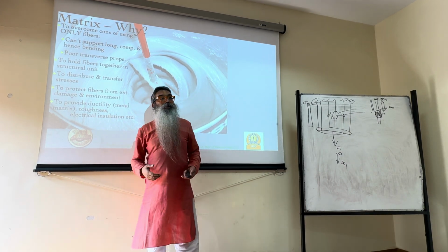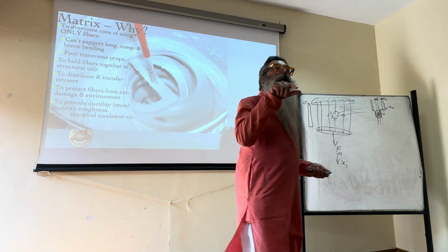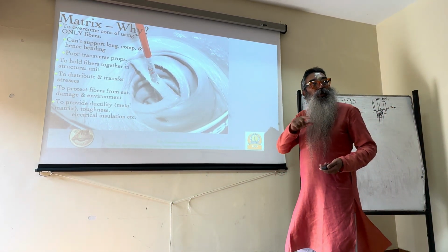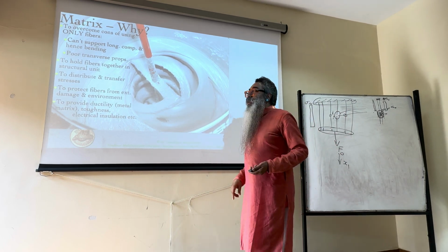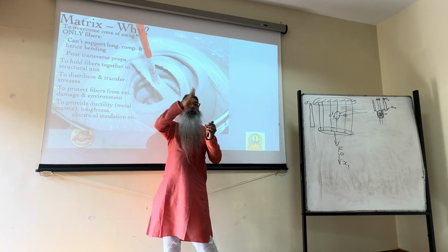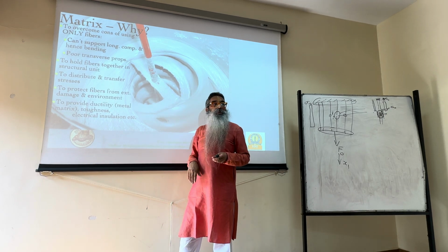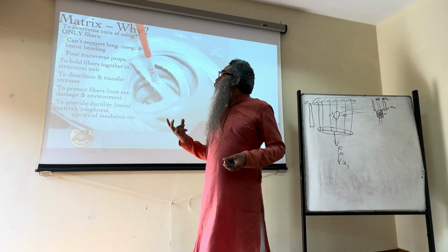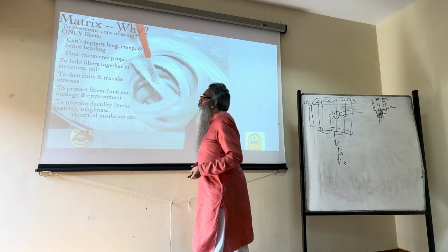The other thing is in terms of the energy storage, because it's a brittle fracture for polymer matrices, the toughness is very low because it doesn't have a spread in the inelastic regime, and therefore the stress strain curve abruptly stops, and therefore the area under the stress strain curve, which is a measure of the energy per unit volume, is much lesser, which is the toughness is much lesser.